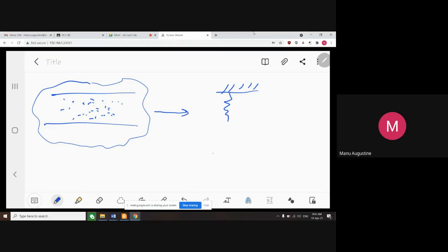So you said that whatever elasticity was existing inside the component vibrating, I converted it into a spring of spring constant K. Now, whatever viscous damping was being offered by the real fluid in your system, you converted this viscous resistance in the form of a representative damper of damping constant C. So we see that in the case of viscous damping, you were very easily able to convert the real world system into a mathematical model.